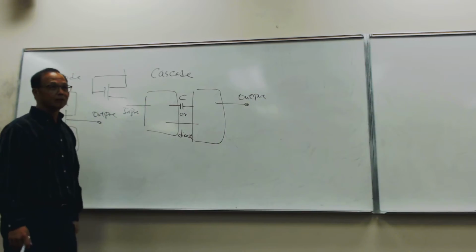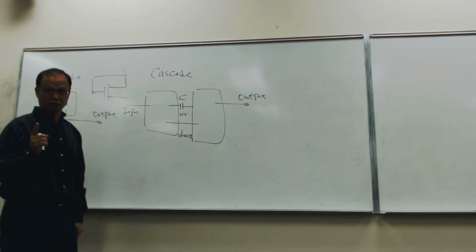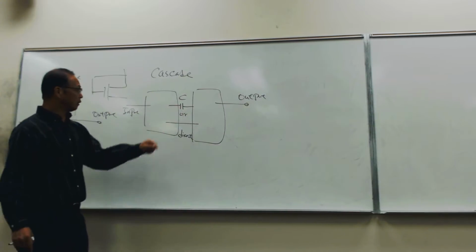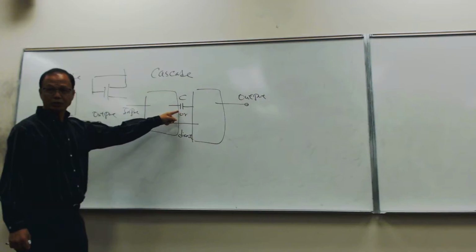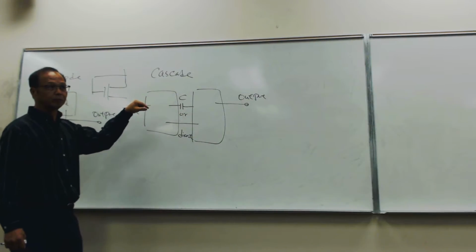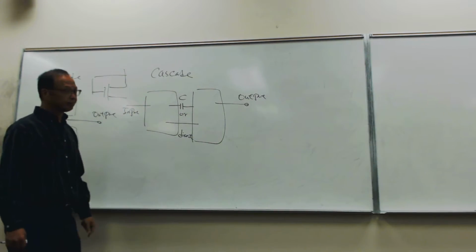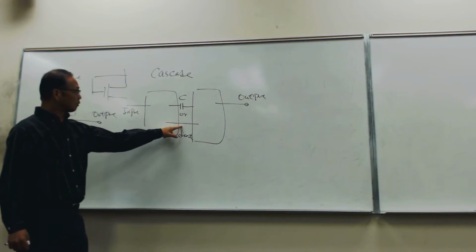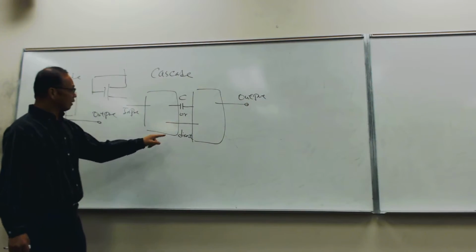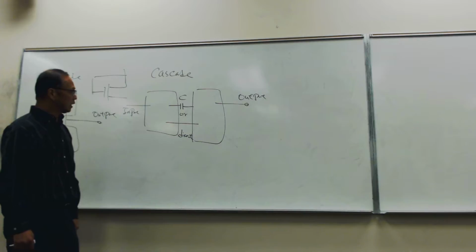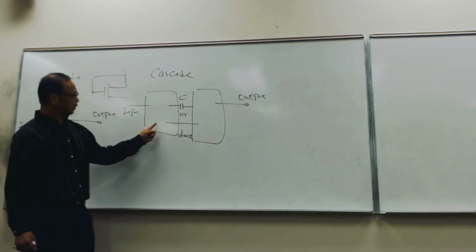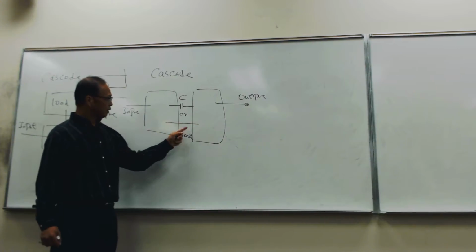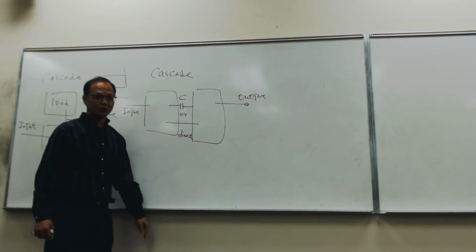As far as the DC is concerned, because this is open. But you do have to put a capacitor, and the capacitor can have some parasitic effect. The direct coupling does not require a capacitor, but it can make the DC analysis more difficult, right? Because the first stage is connected to the second stage.